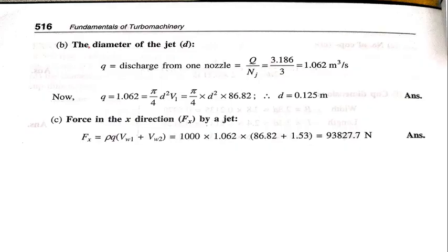Since you have this type of problem also here, this problem also I'll be discussing here. Because you have already derived the problems using velocity triangles, this problem might come for you. So for that reason, see here the 3 jet Pelton wheel. They had given here the number of jets as 3 is required to generate 10,000 kilowatt under a net head of 400 meter. So to generate 10,000 kilowatt, shaft power is what? 10,000 kilowatt.